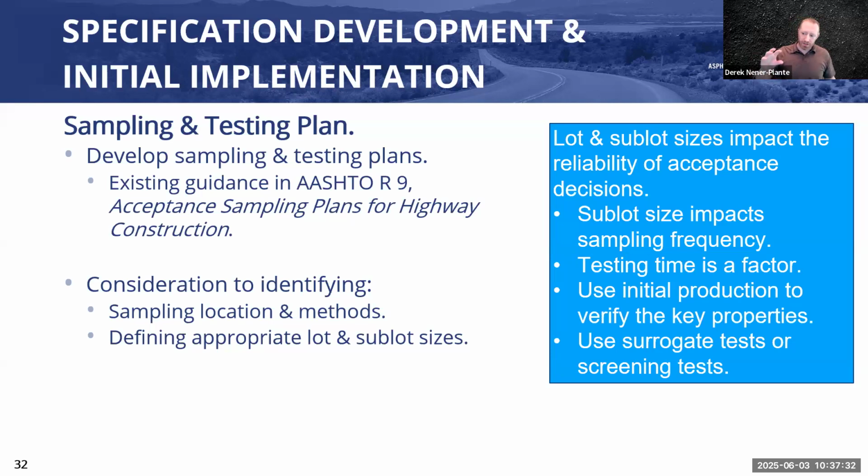But a key reminder, and let's put this in the context of balanced mix design testing, right? Okay, we're often going to need more material than we have before, versus if I was going to run a couple Rices, a couple asphalt contents, maybe, you know, do some voids, etc. Versus if I'm going to run CT, RT, plus maybe some of those other tests, we're going to need more material. All right. Location matters because of the whole idea of reheating, aging, and we're going to talk about that when we talk about lessons, right? How does that feed into this?